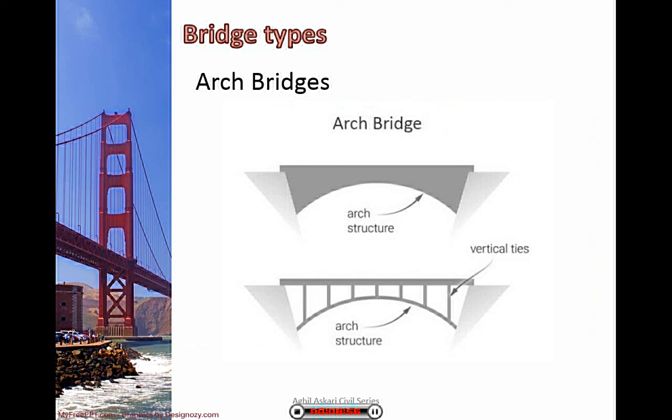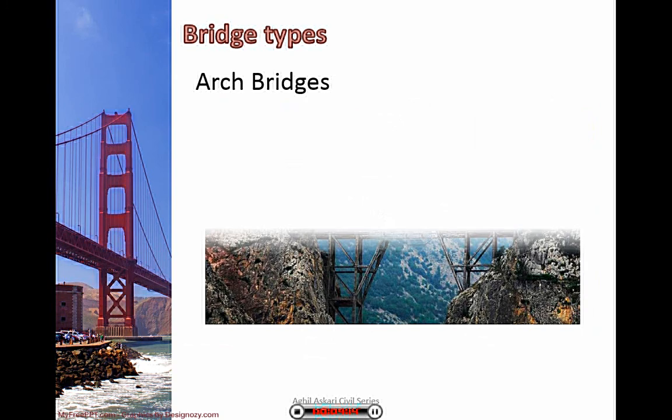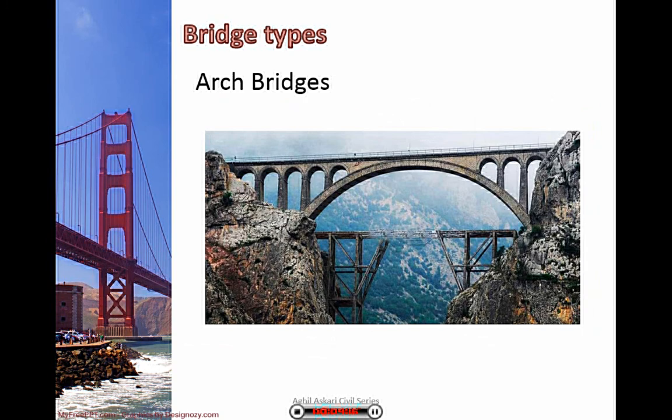The lateral pressure created by the arc span is transferred into the supporting abutments. It is therefore essential that these parts of the bridge remain solid, intact, and well-founded. You will see many arc bridges with decorative brickwork, which is an integral part of the design. Simple yet so very effective, an arc bridge can carry everything from pedestrians to heavy rail.